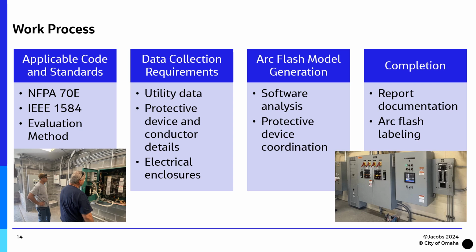After the site visits, the data was compiled to generate an arc flash model using SKM Power Tools for Windows, and other analysis efforts were rolled into this arc flash evaluation. The final step was report documentation and arc flash labeling on equipment.